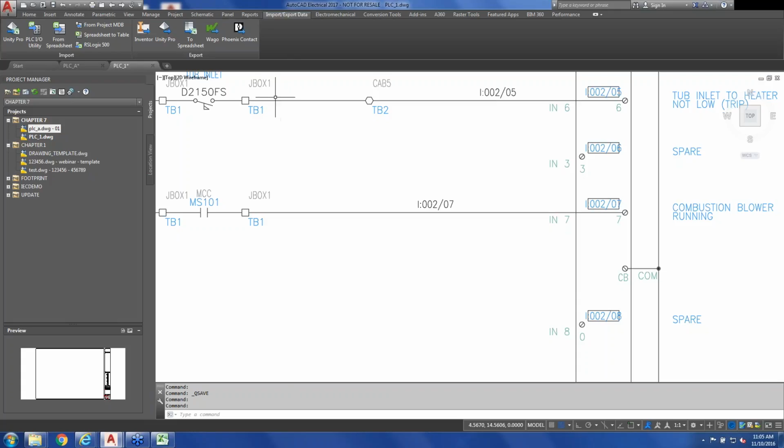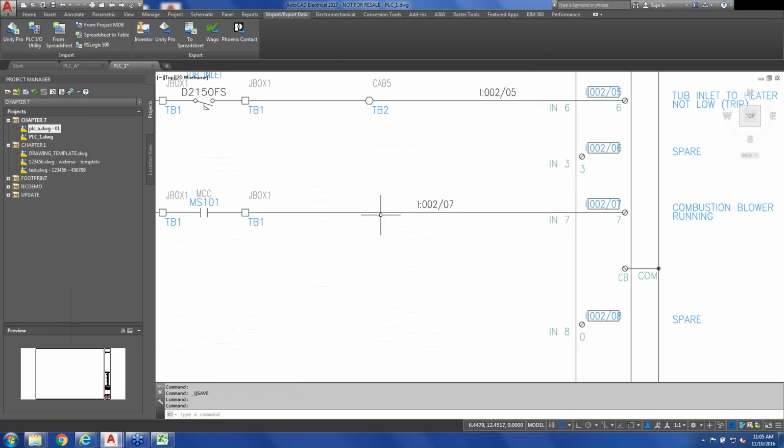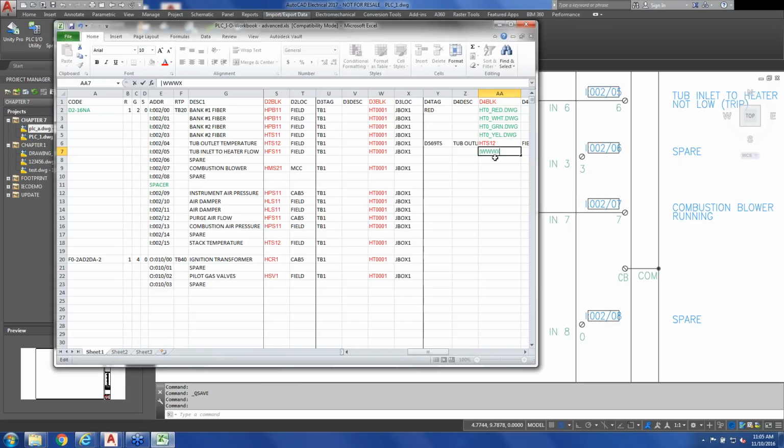So a W here, it starts off, it goes from top to bottom, from left to right. So it would be W, W, and then an X would trim this wire, and then a W would keep this wire. So I'm going to keep this on either side of the top of the wire, and then I'm going to trim to the left and keep to the right. And that's what this is showing here. If I wanted to reverse that and trim the wire down to the bottom right, I would switch the order of those, where it would be W, W, W, X.